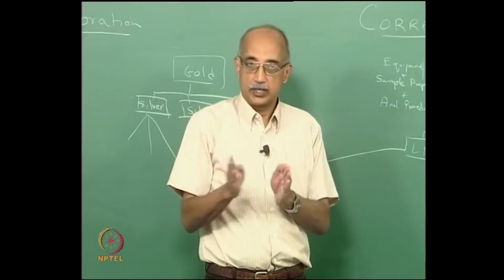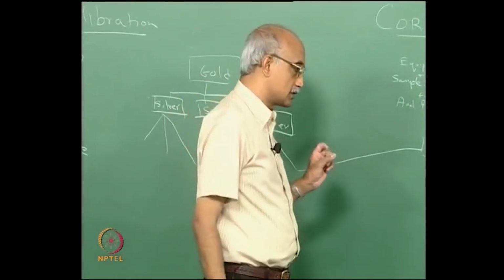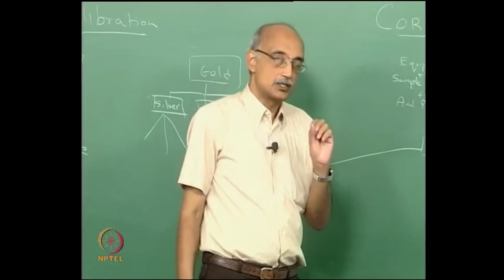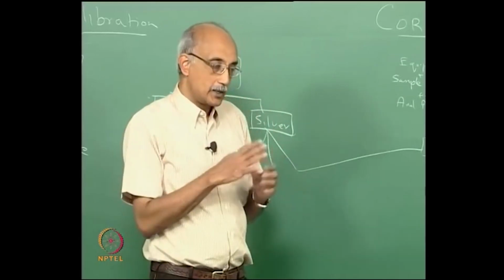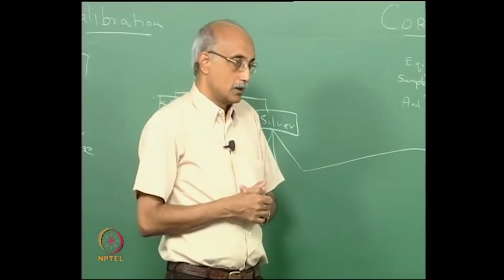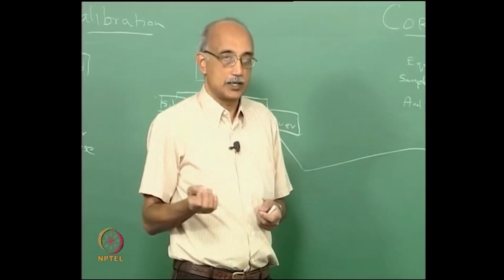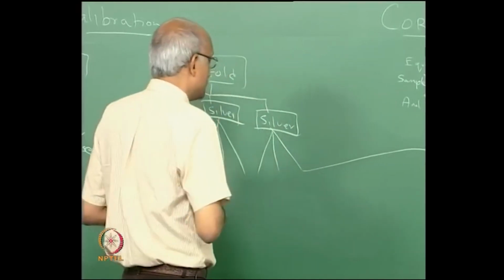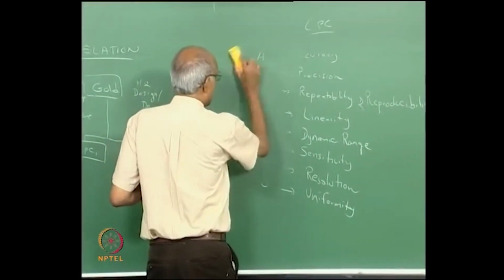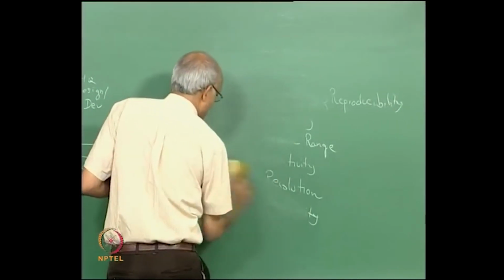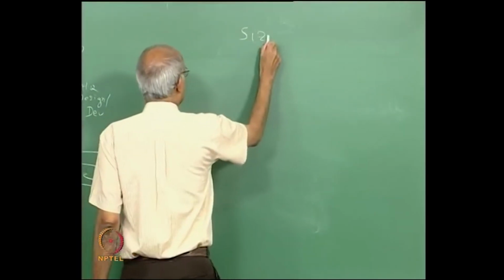Now those two are again very, very different, because if you are only doing count calibration, then that is once again primarily a measure of the sensitivity and other properties of your instrument itself. You can prepare a set of standards which may be particles of a known size, and by the way, the most commonly used standard is polystyrene latex. PSL, as it is known, is widely used as the calibration material for size calibration